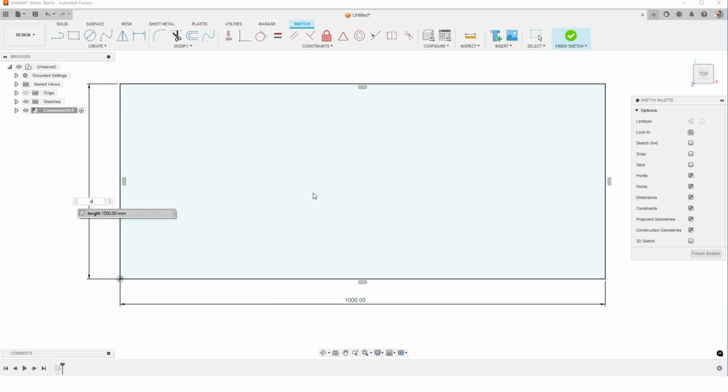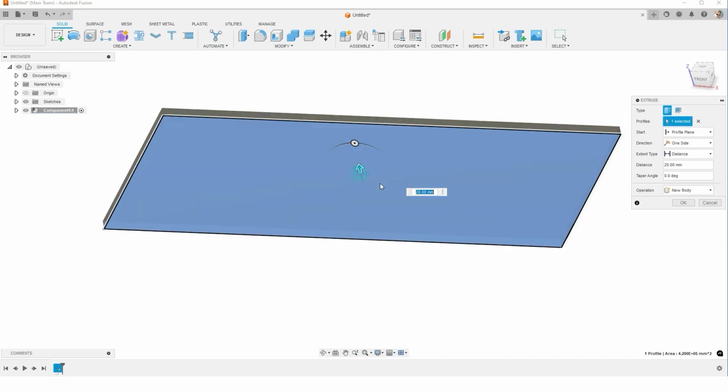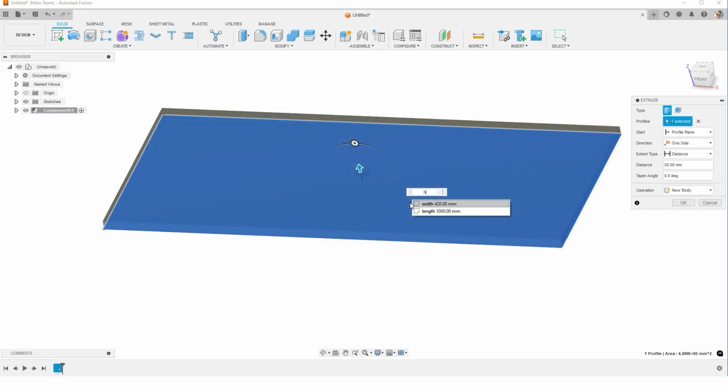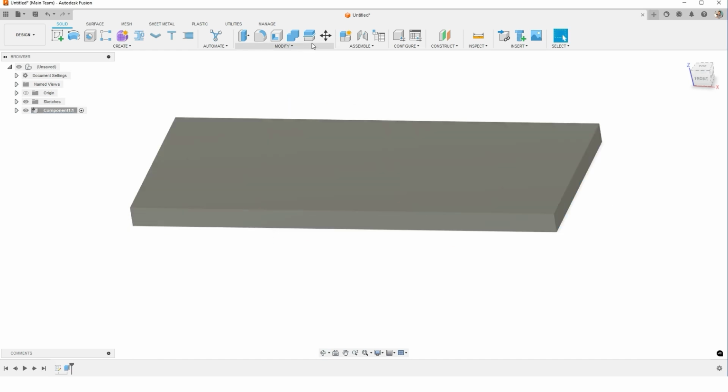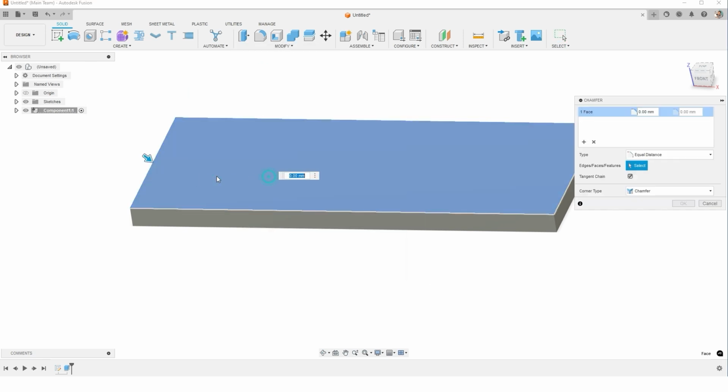So I'm going to extrude this whole thing and even configure that height of the box or depth equals 50, and then we'll add our chamfer. So we have this component, and what we're going to do is use the parameters to drive this. Let's chamfer it real quick.